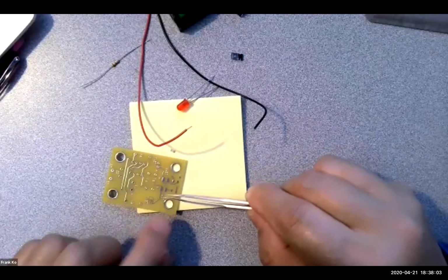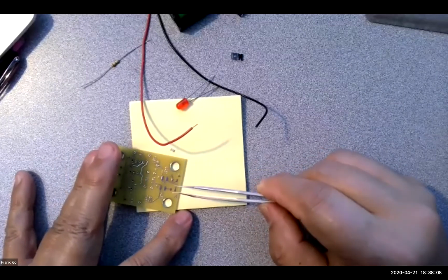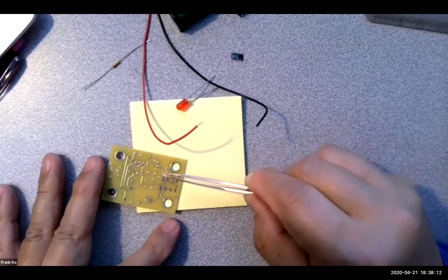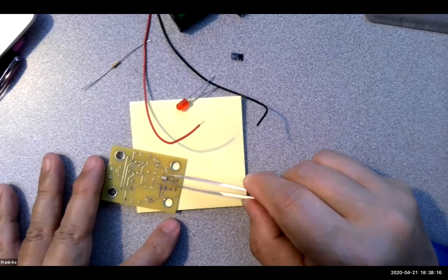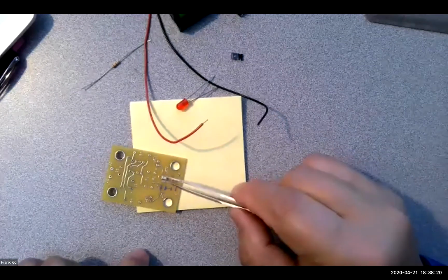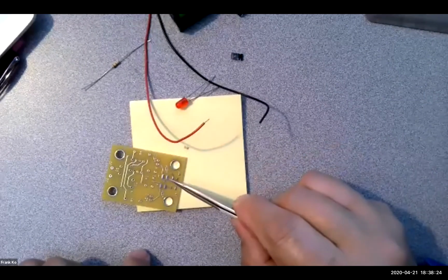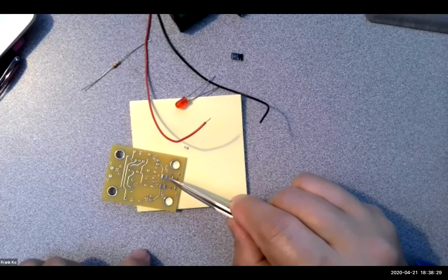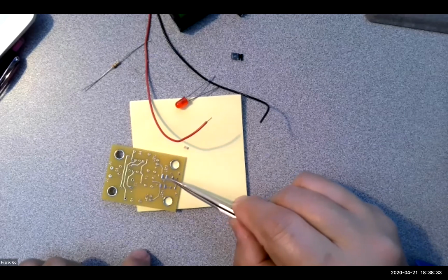And it's marked LED 4, LED 3, and you have some surface mount components, your surface mount LEDs. This has to sit right on that pad in order for you to do the soldering. So my recommendation for you all when you go to do this is to put a spot of solder on that pad first. There are 2 pads, a positive pad and a negative pad. Put a spot of solder on the pad first.